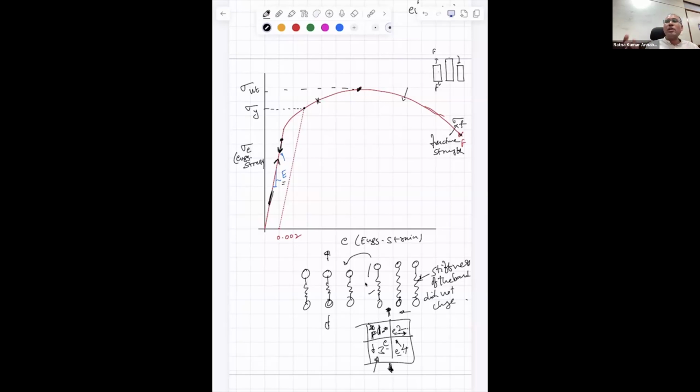All the deformation during unloading should only be elastic, unless it is continued in the unloading direction beyond zero stress. If it is unloaded to zero stress, then you have to unload along that path. And the slope of that line should be the same as E.